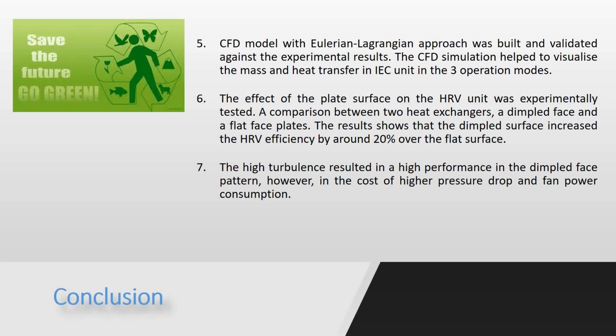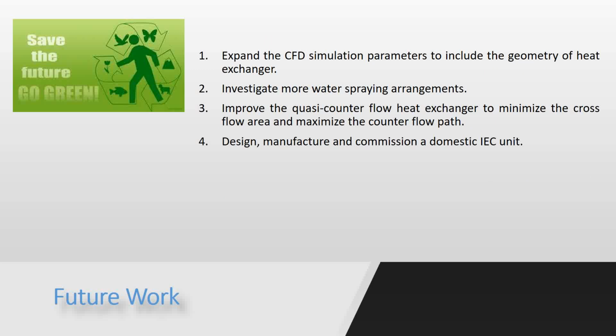For future work, again, expand the CFD simulation parameters to include the geometry of the heat exchanger. But the only problem is that I would not be able to make the gap between the plates less than 6 millimeters, because the sprayer will not work in that case. Investigate more water spraying arrangements. I have multiple ideas created during the study. Improve the quasi-counter flow heat exchanger to minimize the cross flow area and maximize the counter flow path.